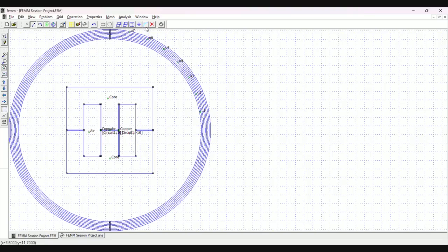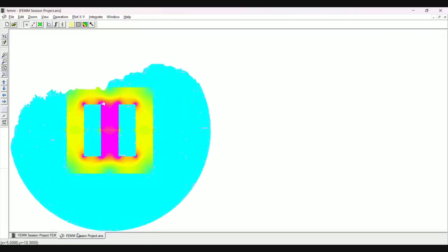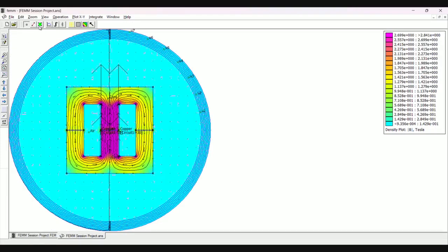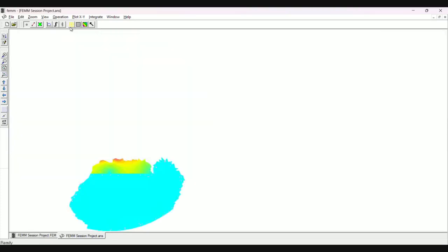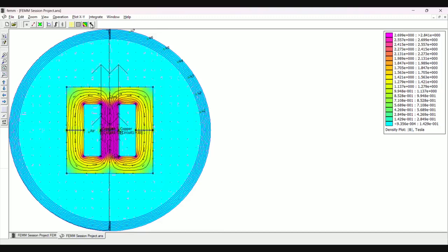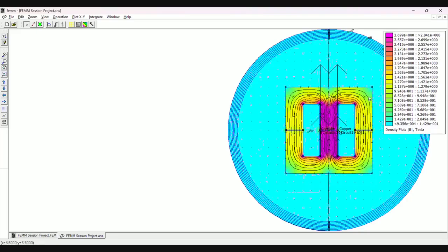So these are the tools for FEMM, sorry again, I forgot, these are the tools for FEMM and the answers. You have again the point, line, and this one you can explore. This is a graph, integral, and this is the circuit parameter. And then here you can also see the mesh. That is not a big thing, so you can just turn it off. The flux lines, vector plot and the flux density plot. The same goes with these. Maximize, zoom out, selectively zoom, move. And this is a scale. You can compare it here. I don't think it will move. I'll just see. No, it's not moving. So you can move this and you can compare.